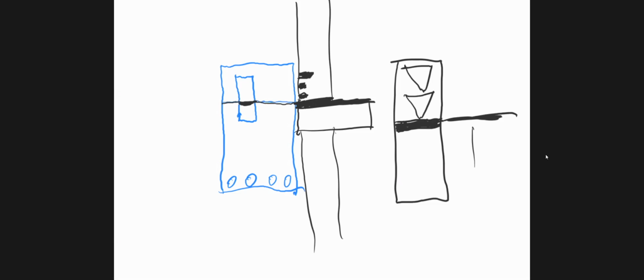There's also a window on the back side of this, so you can stand behind it and point the receiver at the laser, and you'll be able to see that same window on the front of the unit. And if you turn it around, there's a window on the back, so you can stand behind it and see the arrow. So this works the same way. As you lower the receiver, the arrows will disappear, and eventually you'll see the black bar show up with the constant tone. Okay.